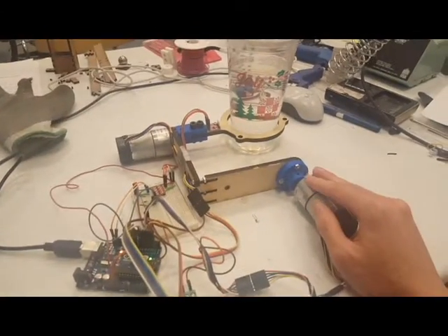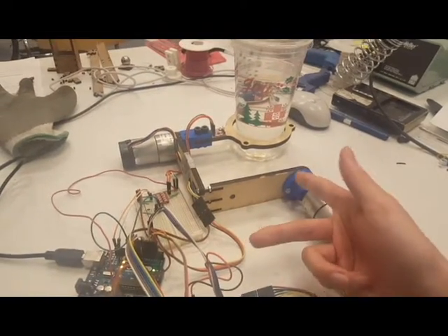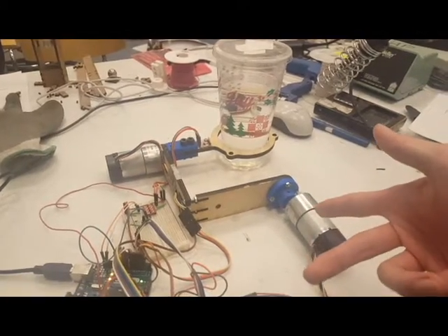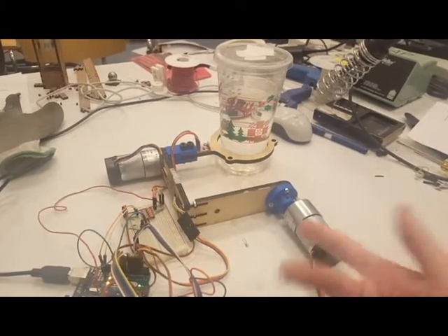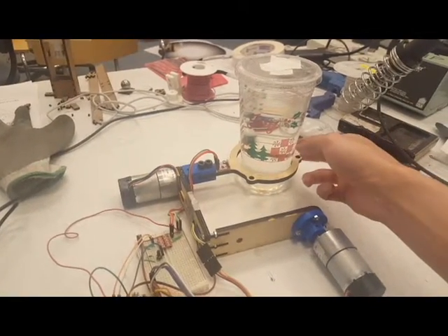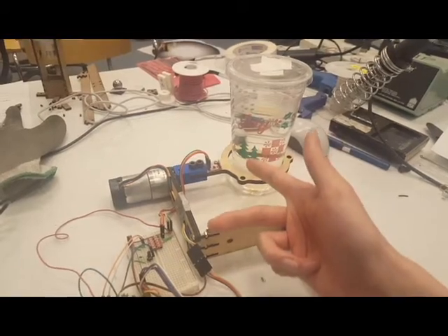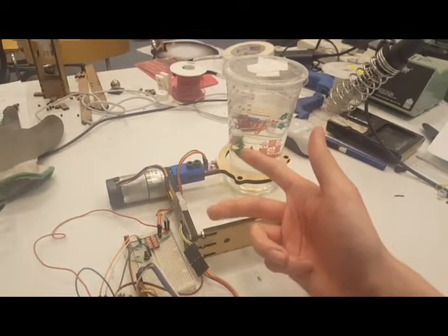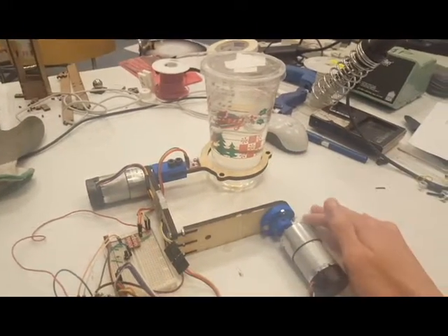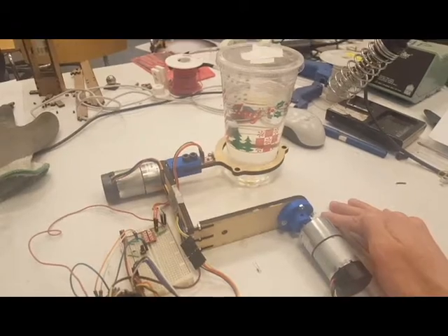As a combination of the operation of these two motors, you can cancel out the effects of your base coordinate orientation such that the instability in your base coordinate system will not affect the coordinate system of the cup, or the frame of the cup. It is going to maintain stability over time, staying parallel to the ground plane and orthogonal to the gravitational vector, which means it is going to prevent spilling the coffee.